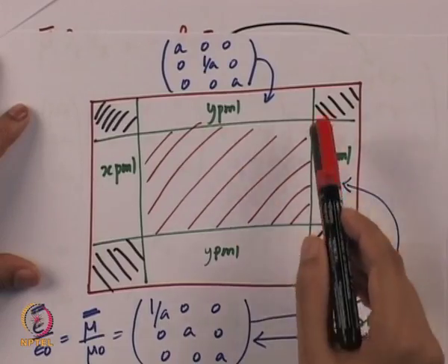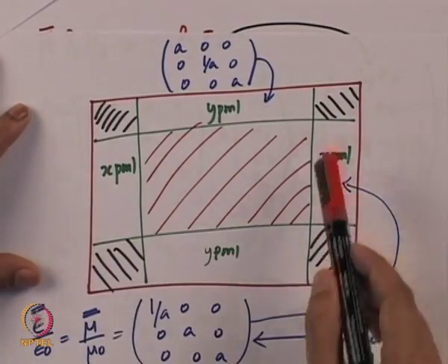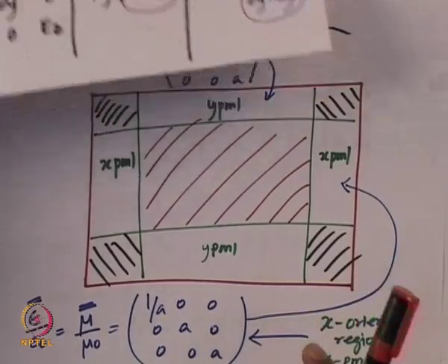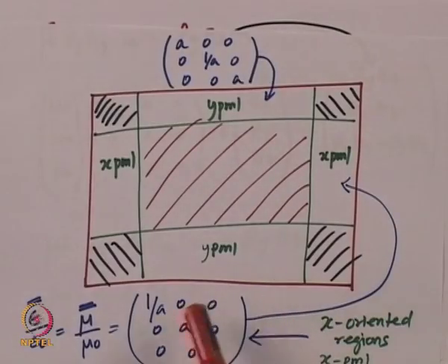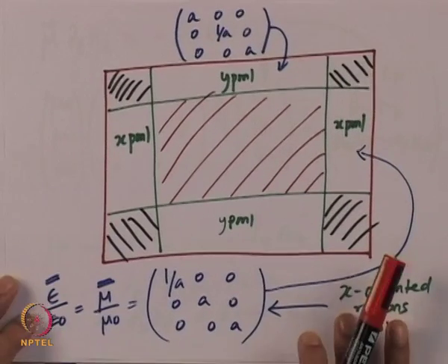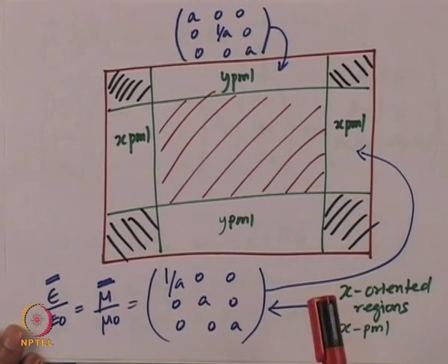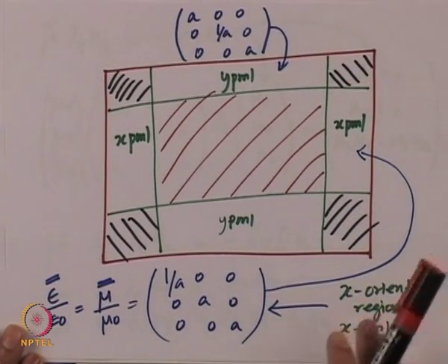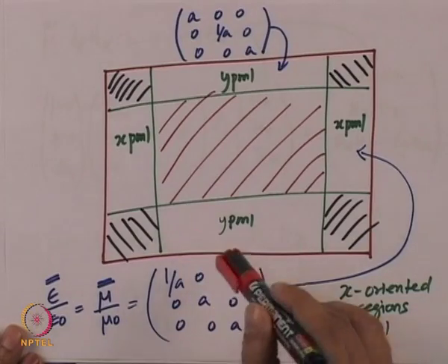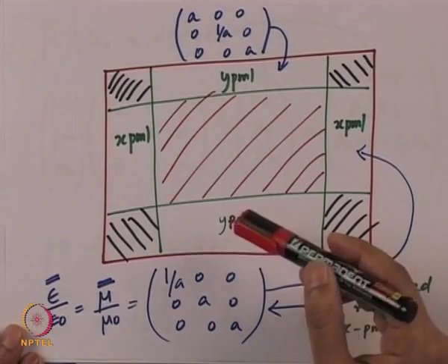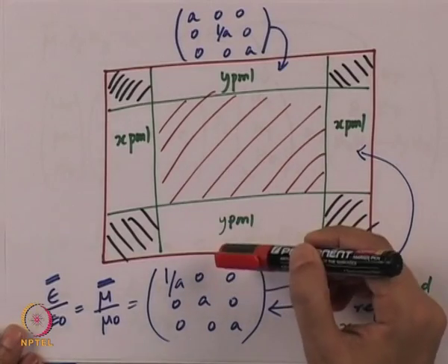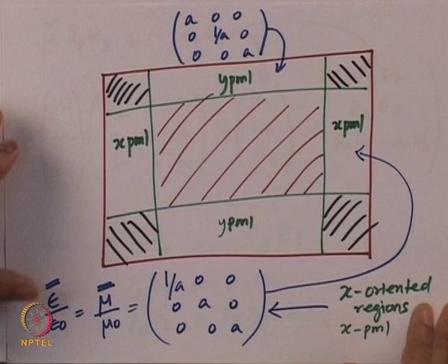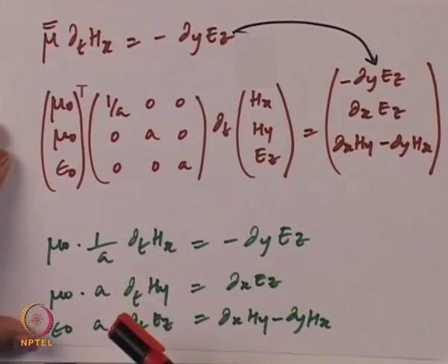When we go into any of this PML domain, the Maxwell equation will follow the anisotropy model that we have accepted. So this is going to be the permittivity and permeability values. Because of this, if I have to model a PML and model the Maxwell equation in the PML, I have to inevitably start with the setup we have given here.